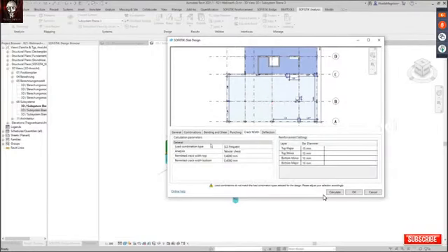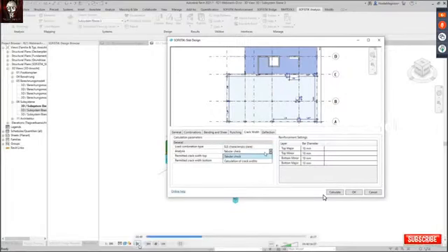And now we go into the serviceability limit state design with crack width design. Here, important, as soon as you talk about serviceability, you can select several of the combination types, because we divide between characteristic, frequent, and non-frequent combination type for serviceability.